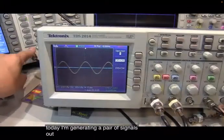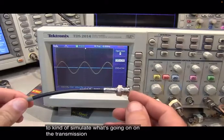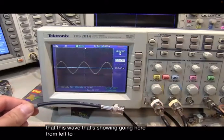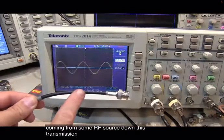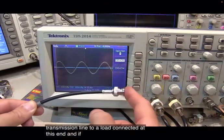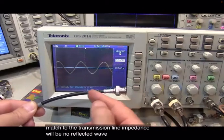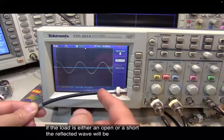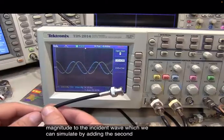I'm generating a pair of signals out of my function generator back here to simulate what's going on on the transmission line. So let's picture that this wave going here from left to right is the incident wave coming from some RF source down this transmission line to a load connected at this end. If the load is a perfect match to the transmission line impedance, there'll be no reflected wave. Of course, if the load is either an open or a short, the reflected wave will be equal in magnitude to the incident wave, which we can simulate by adding the second channel here.